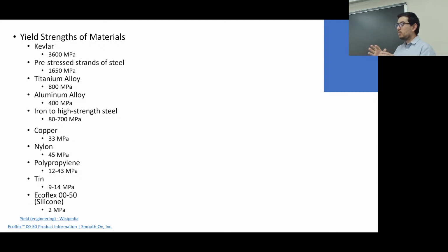So steel is magnificent because you can change its strength just by heating and cooling, or even stressing it plastically, and it's often at the outsides of the material where that is most prevalent, and that's where the stresses are often the highest. So there's this very nice synergistic behavior.